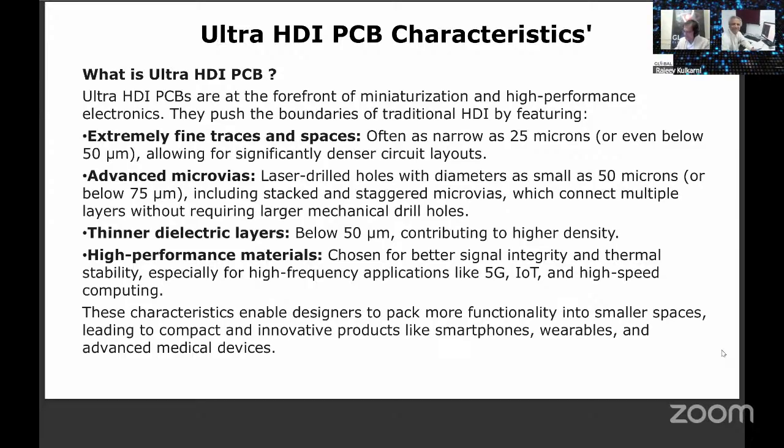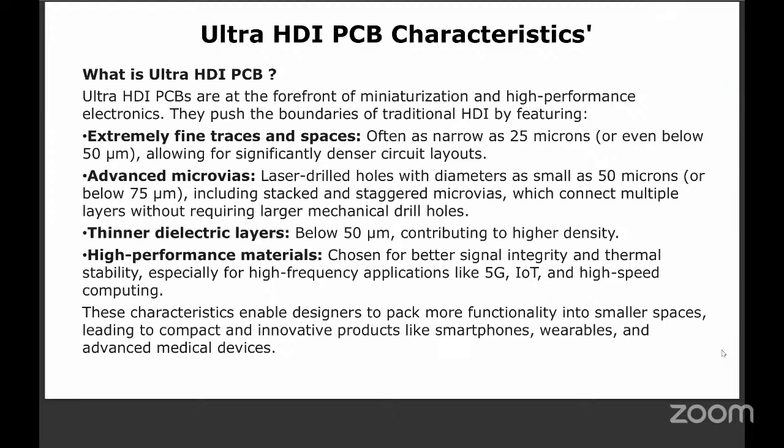Yeah, that's right. And then the dielectric layers, which are less than 50 microns. People have gone less than 50 microns, but UL has stopped approving anything less than 50 microns. If you want a UL certification, you have to stay at 50 microns or more. So that's why it is sort of stuck over there.